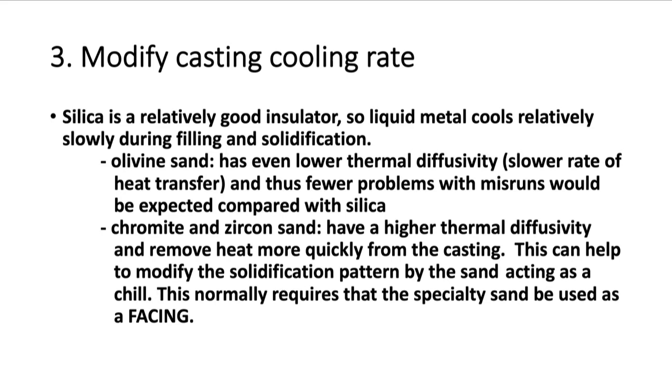So that's refractoriness. That's some of the things that can go wrong. But generally, high purity round sand grains give you higher refractoriness, and some of those other specialty sands. Okay, so how about the casting cooling rate? What do sands do to the casting cooling rate?